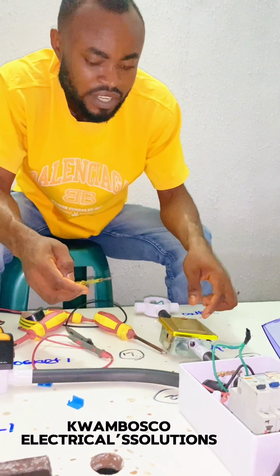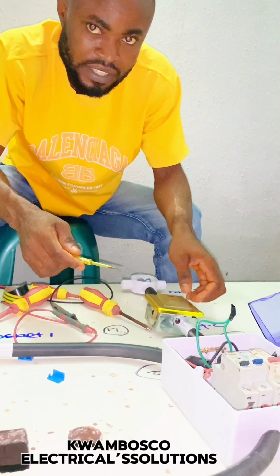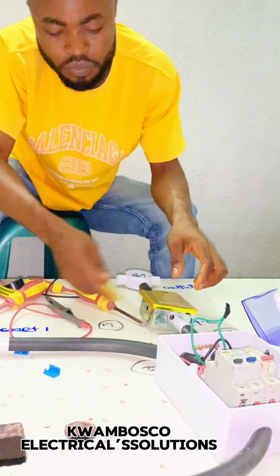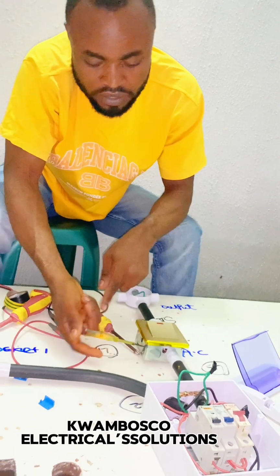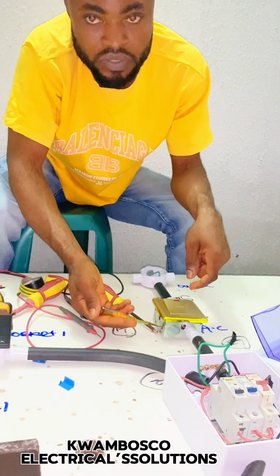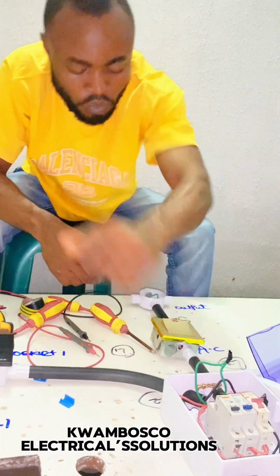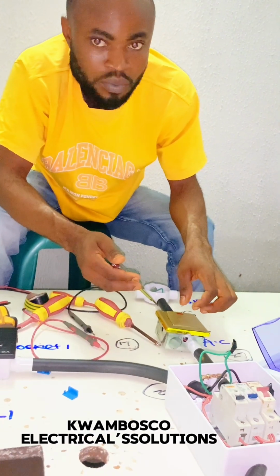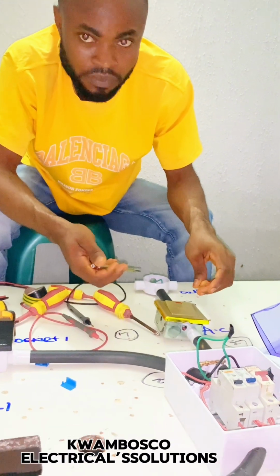So now the second way is to resolve this. The first way, as I had earlier said, is just to screw it off and look for it inside. Now we realize that the live cable was in contact with the knockout bus. You can see, look at it. It's in contact with the knockout bus. That's why it's bringing out light. Now we unscrew this and had to separate it. But the reason why I allowed it to be like that is to show you the second way you can resolve this kind of issue.